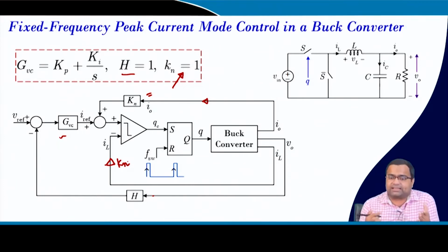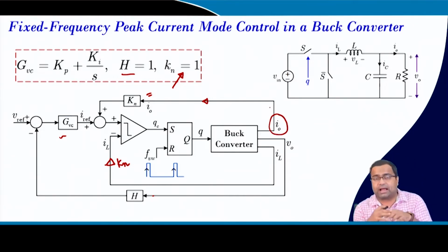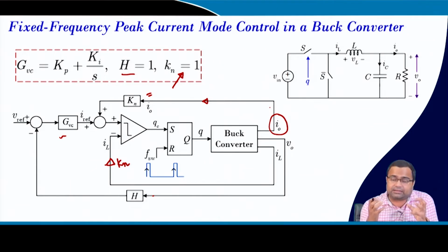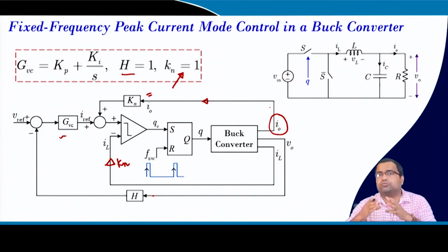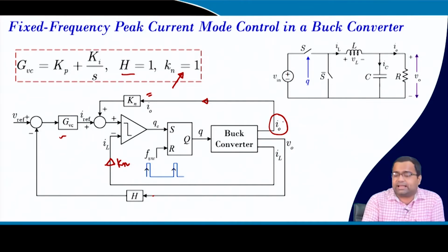Even for processor applications, this load current can be estimated. If you can interact between the power converter, the power management unit, and the actual processor load and task scheduler, in digital control that may be possible. So, you can know a priori that the load transient is going to come, and the step size of the load can be determined based on the task intensity, like how much energy is required. Otherwise, you can estimate this load.